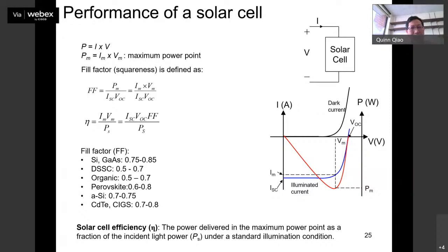So with that point of view, there's one issue. For example, think about perovskite solar cells. You can make small areas like 0.2 centimeter square, and the efficiency can be very high, but when you think about 1 centimeter square or even bigger, the efficiency always drops. Or even if you get some good efficiency, you cannot make a consistent result, or have very good reproducibility. These are the engineering problems. How can you make a large-scale solution-based process that has very uniform crystallinity, very uniform morphologies, very uniform grain boundaries? That can be a big problem.